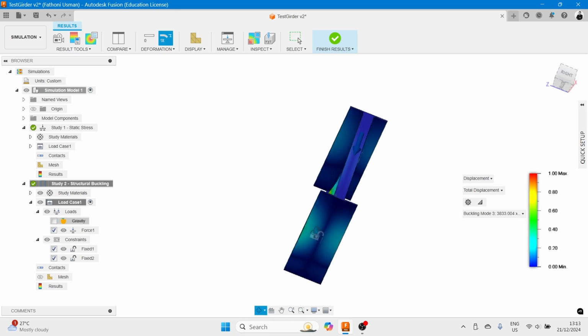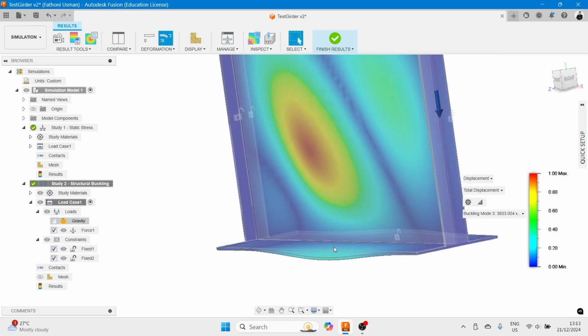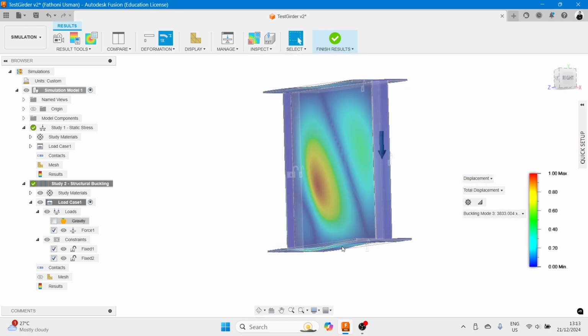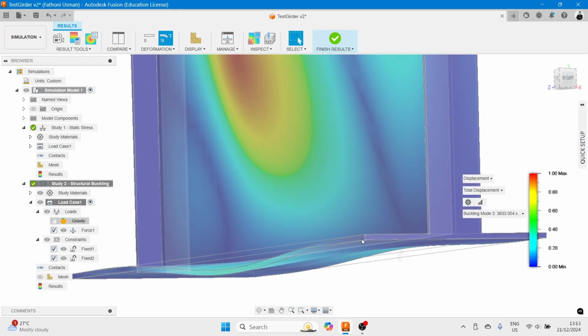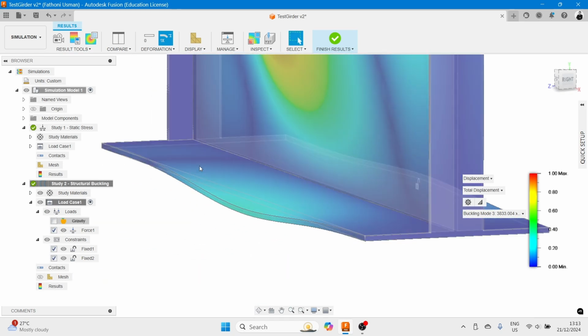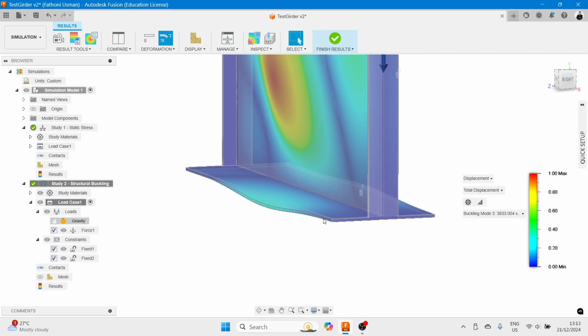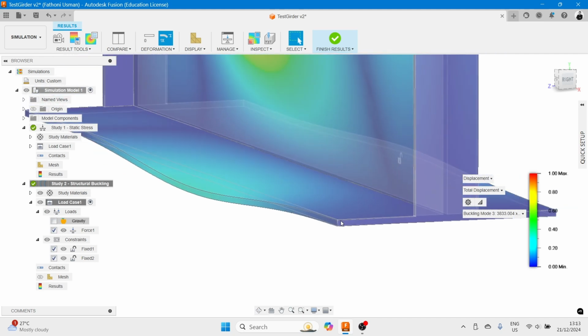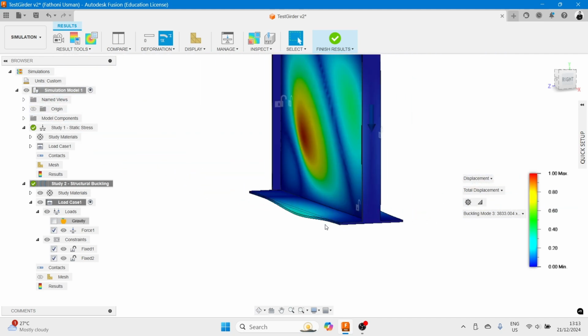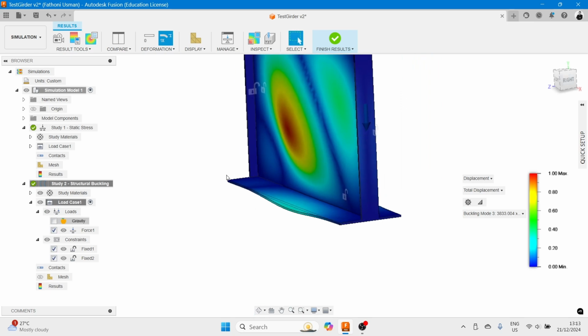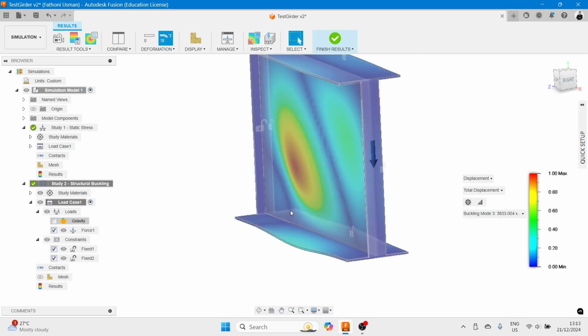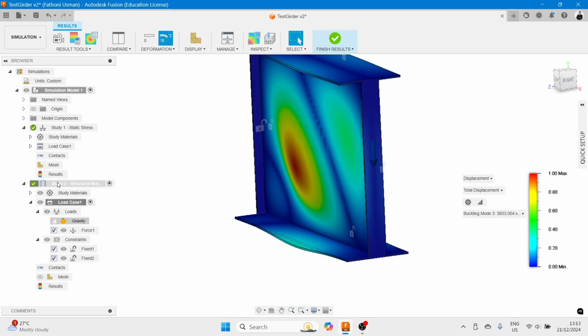But here the buckling also happened in this part. It's because of this one, 10. Maybe I forgot. If I'm mistaken, it's supposed to be 50. So the buckling transfers as well to the flange. It is supposed to be 50 by 800, because this one is 220 millimeter by 10 for the flange. Okay, so then we have this one. Anyway, then we can go for